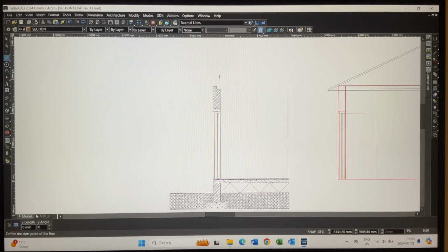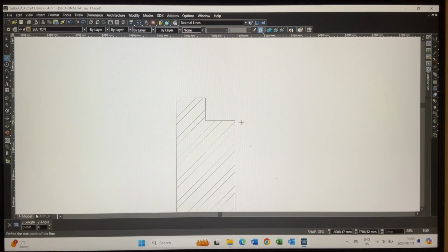Last thing that we need to do is to draw in a wall plate over here. So let's start out and we say that we need a 38mm wall plate. Parallel line, tab 38, press enter, click on that, there we go, 38mm going up over there.